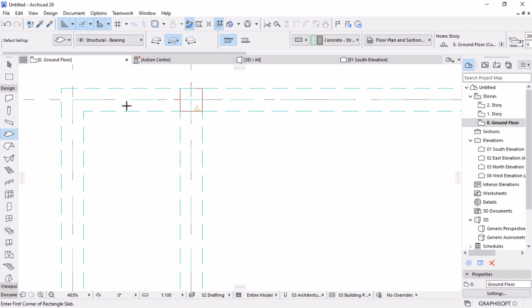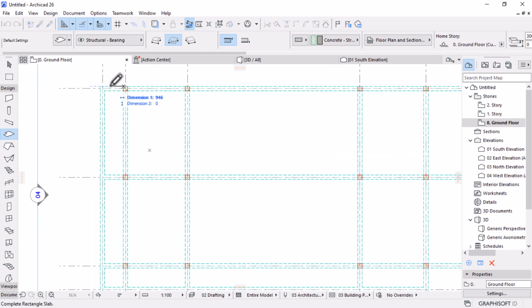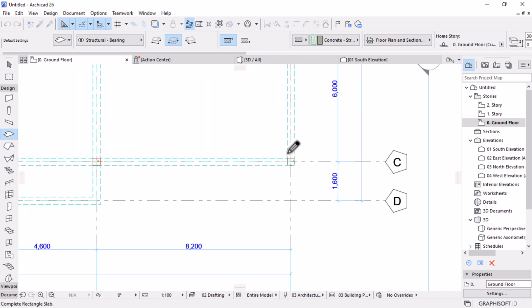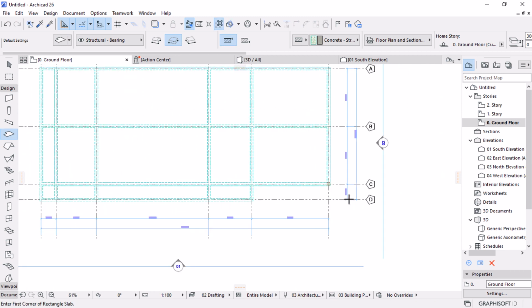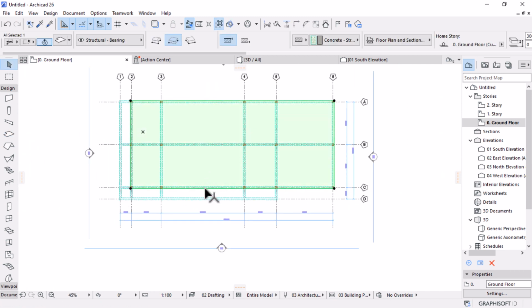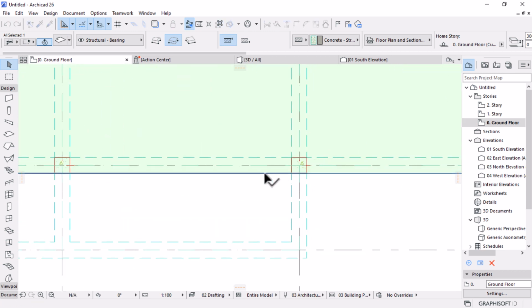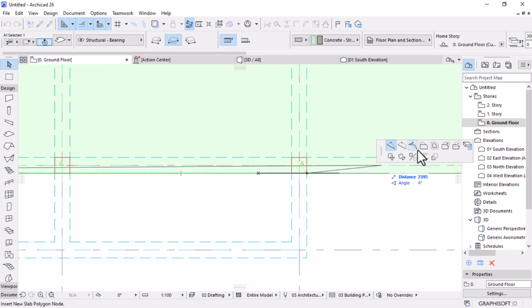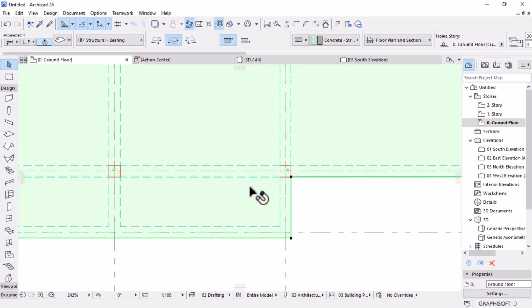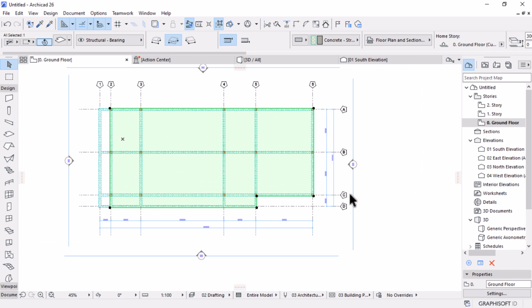The floor slab is going to cover the entire. I'll use the geometry method of rectangle, and then I'll use this corner to place my slab diagonally like that to this edge, and then I could select this one and pick one of this edge. I'll add a point here so that I can now offset this edge to there, something like that. Okay, so now I need to copy this to the other floors.